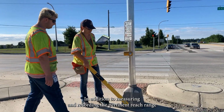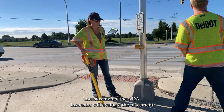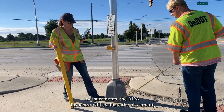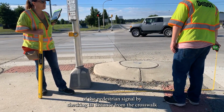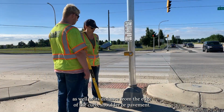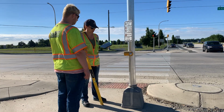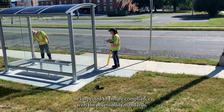In addition to measuring and recording the pertinent reach range measurements, the ADA inspector will evaluate the placement of the pedestrian signal by checking its distance from the crosswalk as well as its distance from the edge of the curb, shoulder, or pavement. Transit facilities will be inspected to ensure compliance with the accessibility standards.